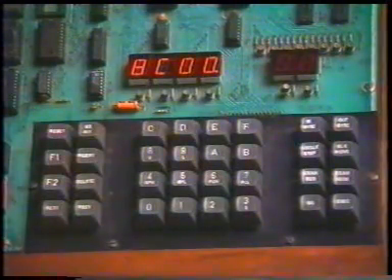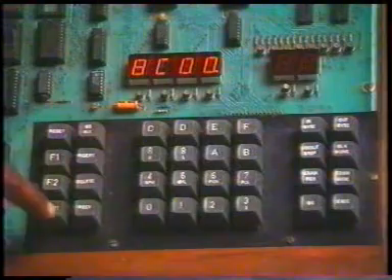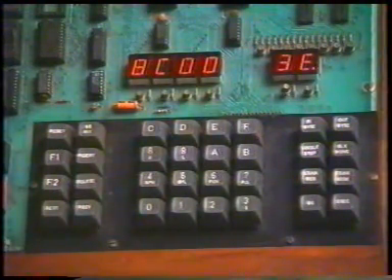A program is loaded in the user area of the trainer kit. The program sets the counter 2 for mode 1 operation and for BCD count. Now let us examine the content of the program. The program starts from the address 8C00. 3E is the opcode for the move immediate A instruction.